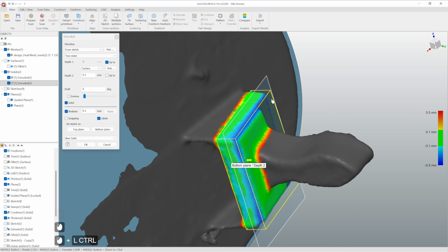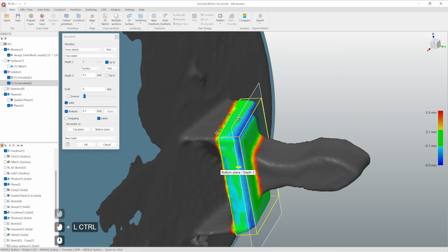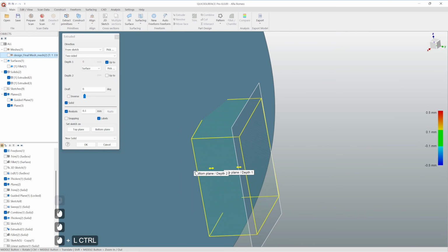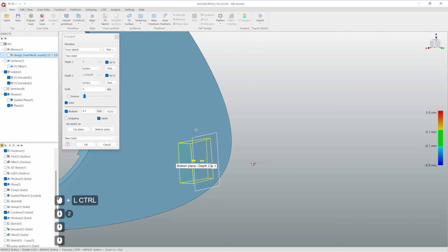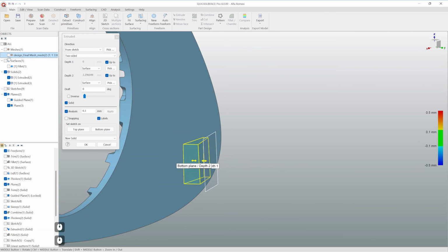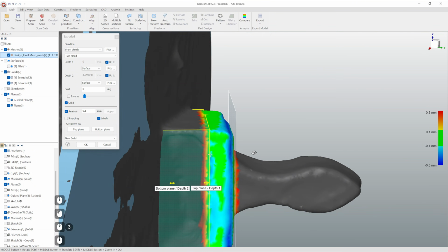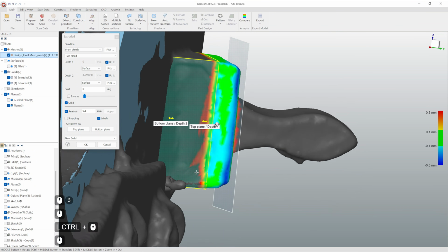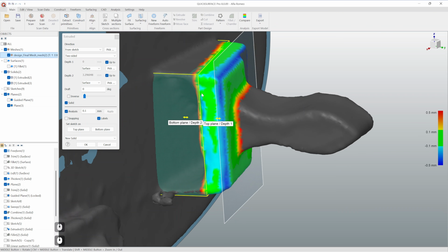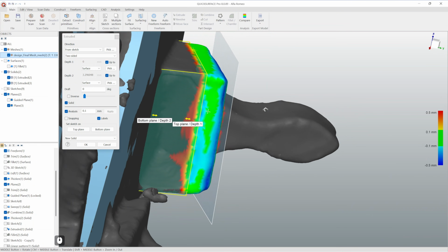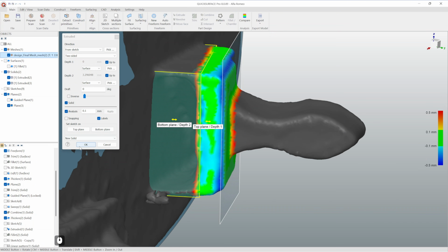So I'm going to snap the top part to my plane, and the bottom part to my solid, like this. But considering we have some empty cavity here, I'm not going to merge all this together, which will create this as an individual solid.